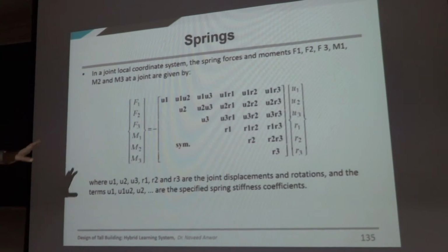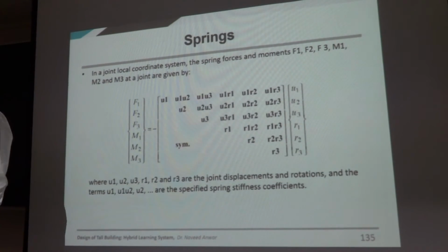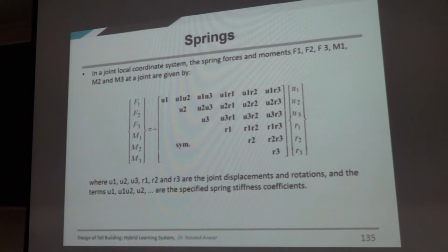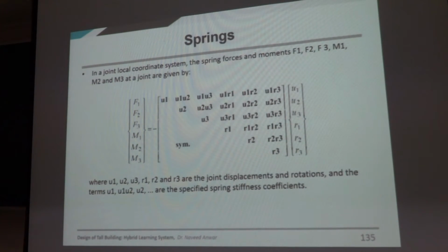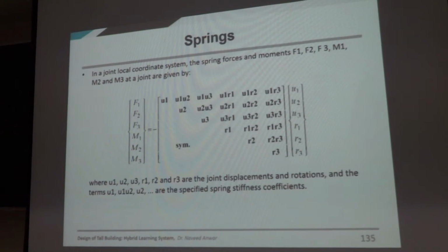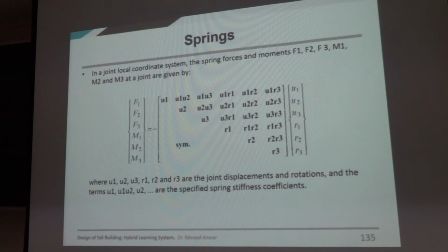Simple one, the simplest model, minimal model is to represent the boundary by springs, which incorporates the stiffness of the supporting system, and we replace the boundary by equivalent springs. So we could have air springs on the side representing air, but the stiffness is so small that we can ignore it. But airplane people cannot, right? For them it is important. Same is the case with liquid. Normally in the water, we can consider the water as a loading, but for the dam, water is not a loading. It is different. It is interaction. So they have to model the water.